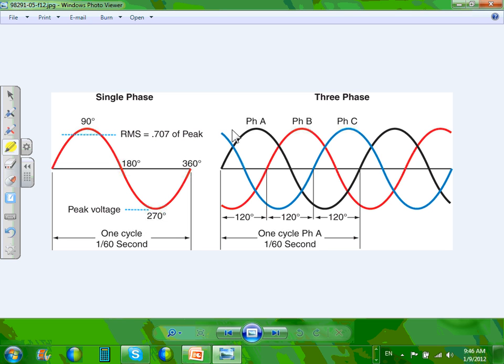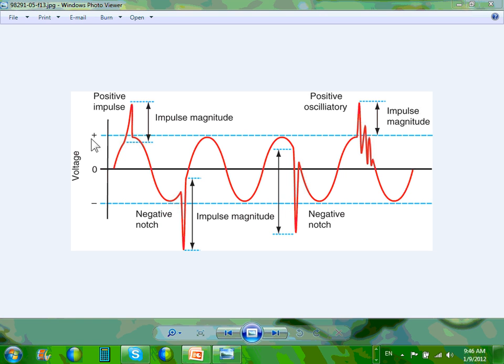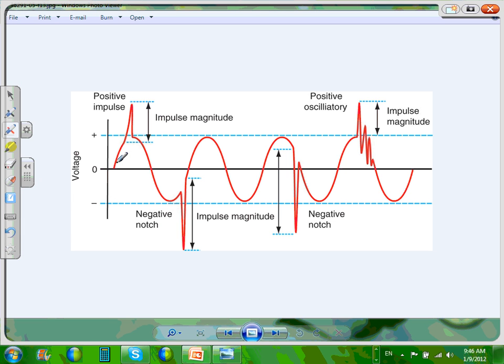What they do is, if you have electronic equipment, the way they digest electricity is different than any non-harmonic. When you put a 120 signal across an electronic device, guys, the way they consume electricity distorts the signal. So if you can see this one here, instead of being a very nice sinusoidal wave as it's supposed to be, and again, this is a pulse really, it's distorted.